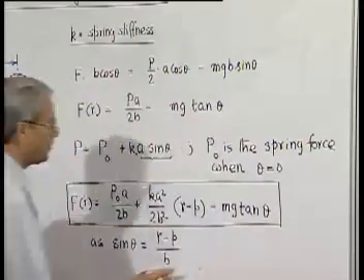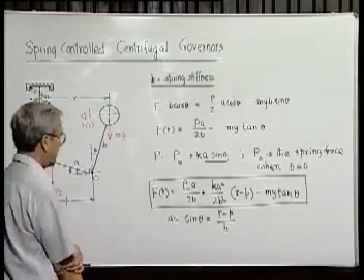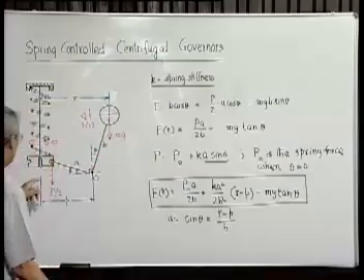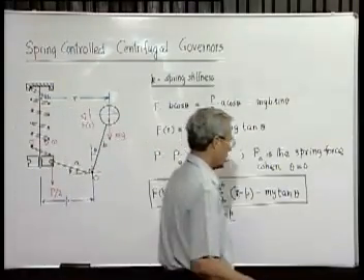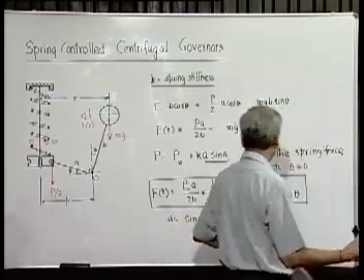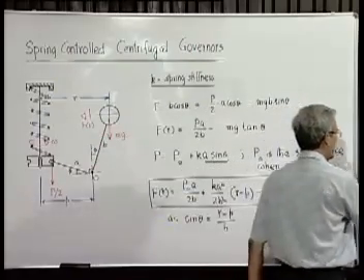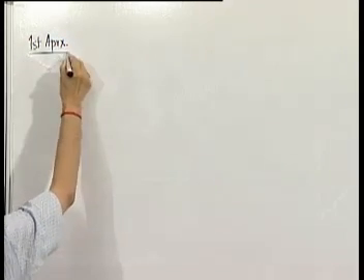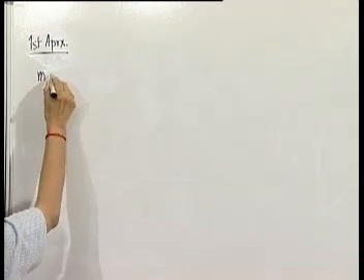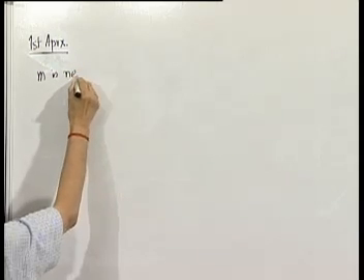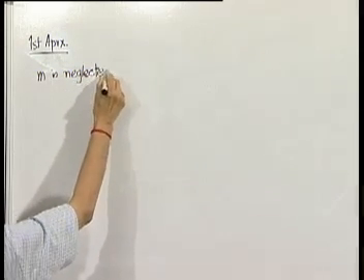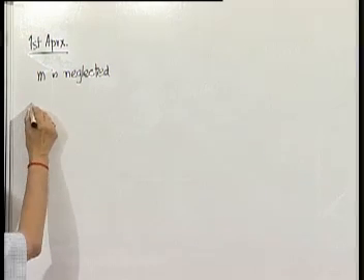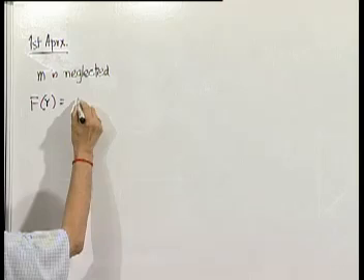Now, if we want to plot, we will have certain problems. As far as up to this is concerned, it is fine. But the theta and r relationship is not that straightforward. So what we can do, let us do a first approximation in which we ignore the effect of this mass, then how the control force looks like. So the first approximation: mg is neglected, the mass is not substantial, then obviously the control force becomes a simple linear function.